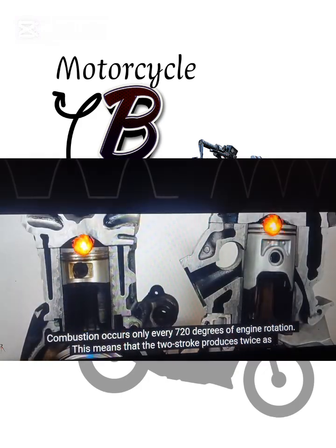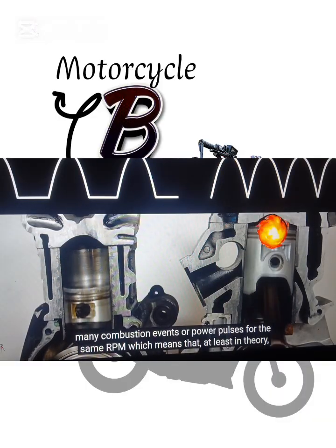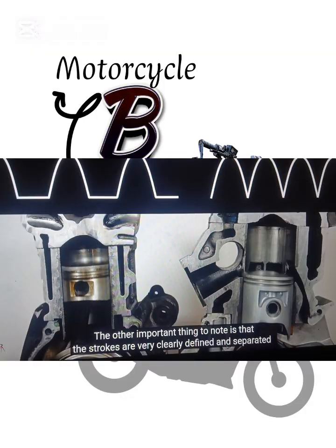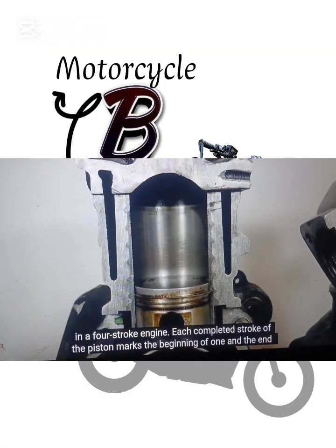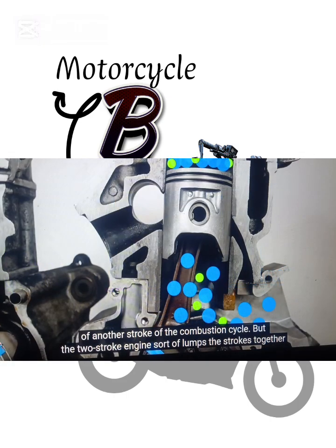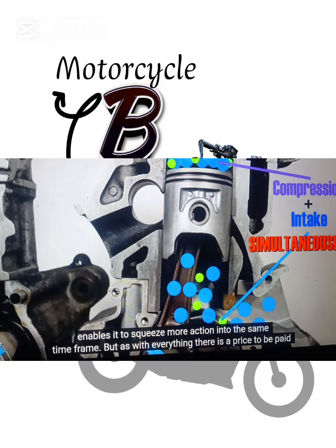This means that the two-stroke produces twice as many combustion events or power pulses for the same RPM, which means that, at least in theory, the two-stroke engine can make twice as much power for the same displacement compared to a four-stroke engine. The other important thing to note is that the strokes are very clearly defined and separated in a four-stroke engine. Each completed stroke of the piston marks the beginning of one and the end of another stroke of the combustion cycle. But the two-stroke engine sort of lumps the strokes together. They overlap and occur simultaneously. The two-stroke is actually multitasking, which enables it to squeeze more action into the same time frame. But as with everything, there is a price to be paid.